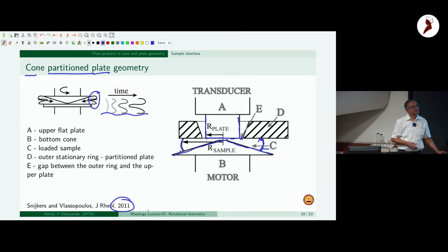Because of very large particles. Very large particles, some 300 microns. And also very high solids loading, right? Effectively, by volume it's 55-60% particles. By weight it is 80%, but by volume it's also still very significant.